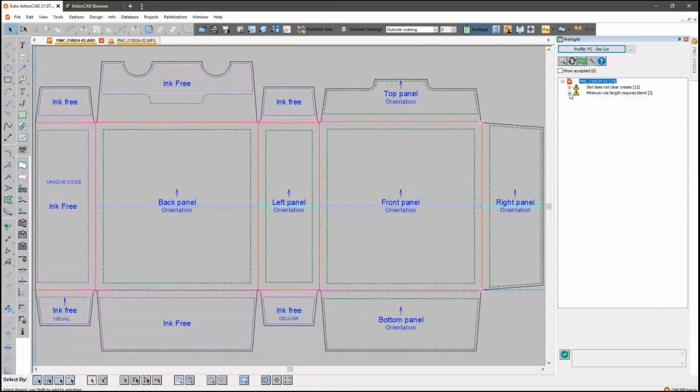But again, all CAD pre-flight is doing is giving a designer the ability to look at something before it goes to manufacturing and make sure there are no anomalies that are going to affect making a cutting die, bending the rule, or even going into a layout in ArtPro Plus. So it's a nice check system. Pre-flight has always been a very graphic term dealing with the artwork, but I think we've done a really good job on the structural aspect, making sure this works before it goes to manufacturing. In that case, everything looks okay with this file.